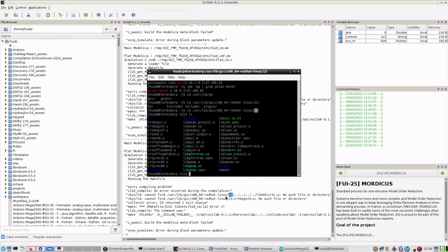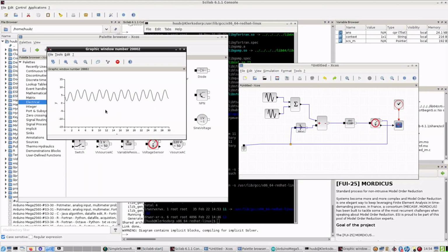So how is Scilab looking into a non-existing directory and into a wrong directory anyway? Once I have found that out, I can go on. I kind of solved it. In Linux terms, Unix terms, I created a symbolic link to the file that doesn't exist, and that seems to work.